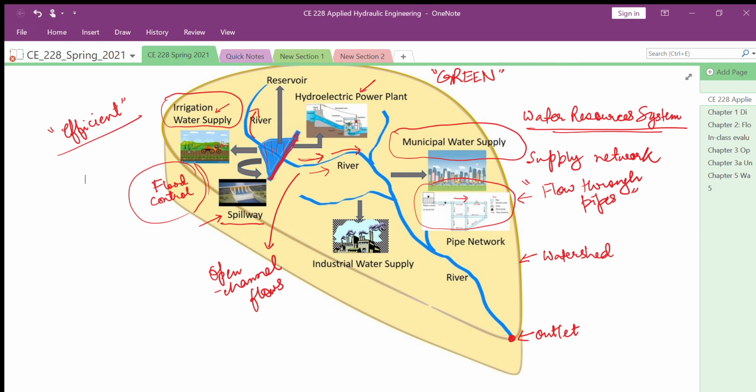Again, let's say you had constructed a concrete canal of, let's say, trapezoidal cross section, like so. This is the water level, and this is concrete, so this is fully lined. Now what happens after many years is that you may have vegetation growing. You see all sorts of weeds growing in canals, even though they are lined by concrete. You can have gravel and silt being deposited in the canals. So as these channels age, their resistance to flow also changes.